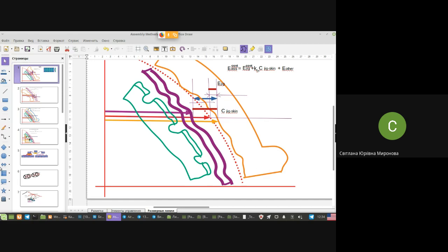I hope you do remember this story that we started to study since the third year, that to provide assemblability, it's not compulsory to have 0 errors of objects. It's enough to have equal errors of objects. If errors are the same, the error of coordination is 0. Of course, both errors of these objects must be inside of tolerances. But anyway, let there be some errors, but let these errors be equal. And that is better in terms of coordination, in terms of assemblability.